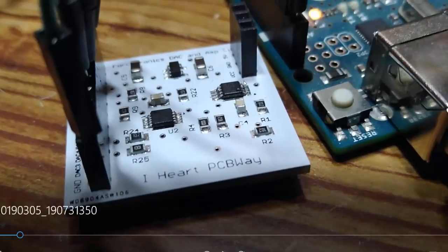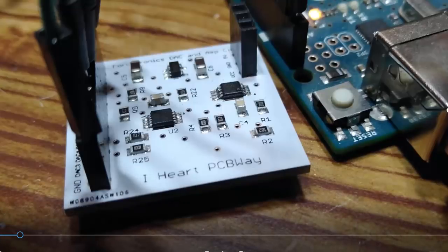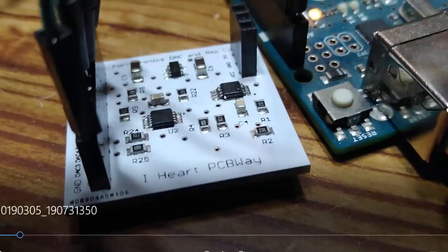All right, let me pause the video right here. Here we're looking at the DAC board I made, which you'll be able to get from PCBWay if you want. And this is the actual MCP4728. And here's a 5-volt regulator to feed the power supply for the DAC. Then here's an op amp I just threw on there, a precision rail-to-rail op amp. What I did is I connected channel 3 and channel 4 to the op amp, and the op amp has a gain of 2 using these resistors. So if you use this board, on channel 3 and channel 4 the output amplitude is doubled by this op amp. Now I don't use this op amp in this first example, but it is used in the second example. What else did I want to mention?